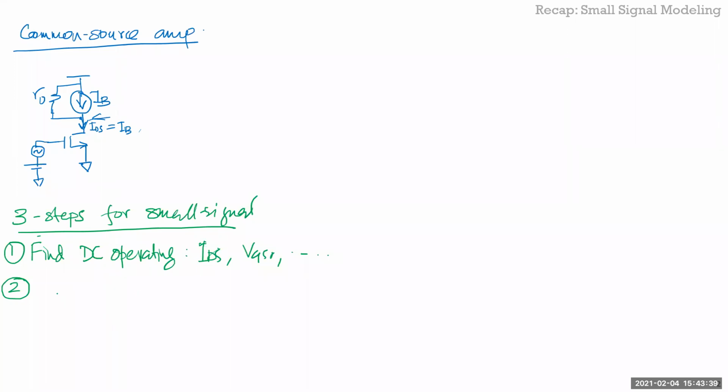Yeah, make the voltage source 0, but put it more generally, you make all independent sources 0, right? So V equals zero, I equals zero, which means that wherever you have independent voltage sources, it is a short, and if it is a current source, it'll be open, right?